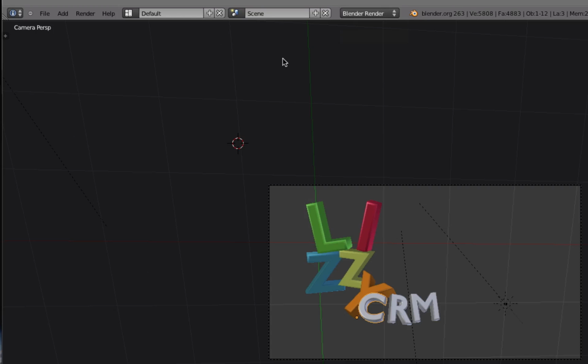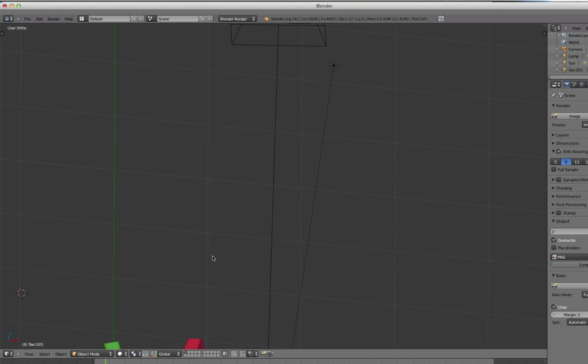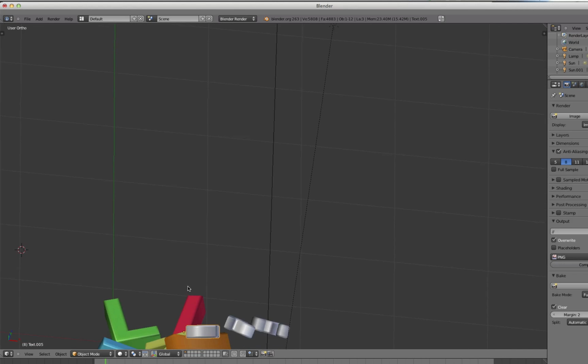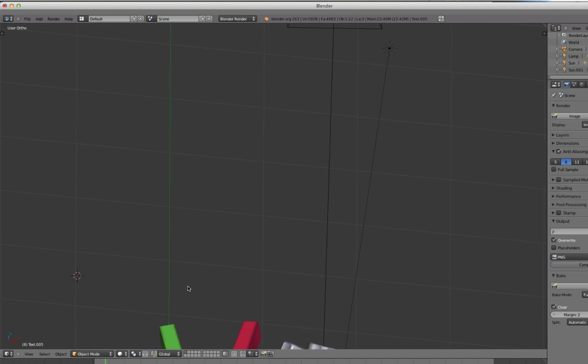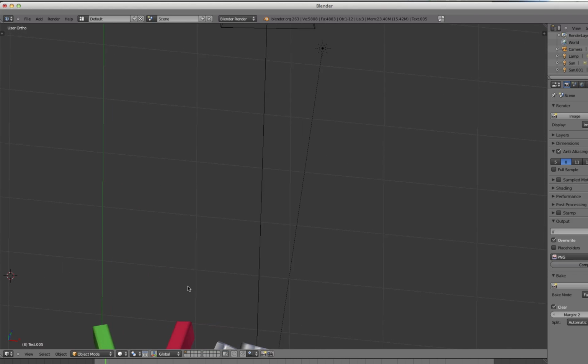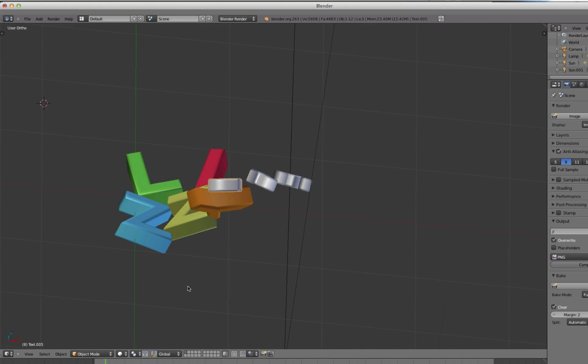Now, I'm going to show you how to move around here and some of the things that we can do. Part of the keyboard options that we changed is I can hold the Alt key down, left click, and it will actually let me scroll around this image. Now you'll notice that it's gone off the screen. If I want to get it back on the screen, there's 4 keys. We've got Control 2, which will move me up. Control 8 will move me back down. Control 4 moves me to the right, and Control 6 moves me to the left. So those are just some keys to learn and remember to scroll around.